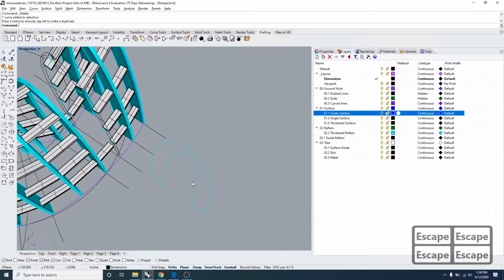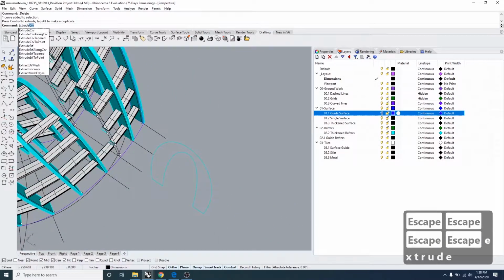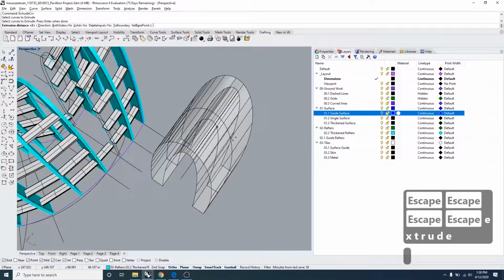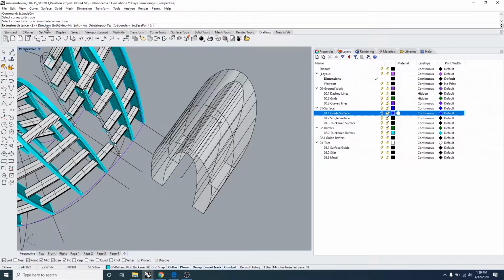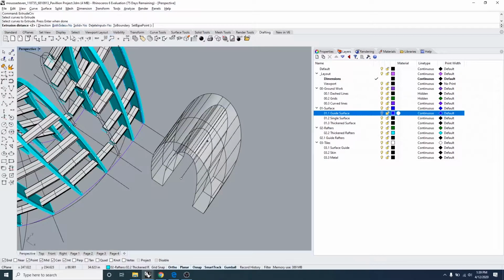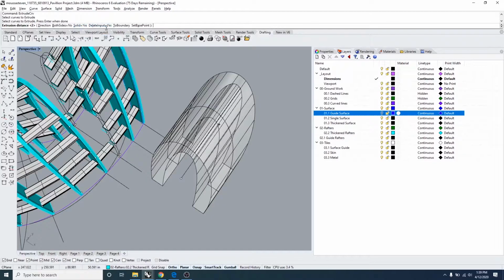Then when I do extrude curve, I would select this object and I would give it a thickness of 2. But before I do that, I just want to bring attention to these sub options here. Notice that the direction is going to be driven by Rhino because of the curvature. Both sides we don't need because we're only extruding to one. We do need a solid, yes, and it's up to you if you want to delete the input or not.